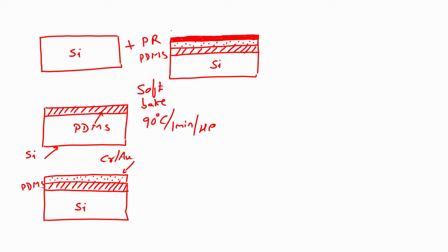After soft bake, I will load the mask to form my chrome gold pattern, and this mask will be a bright field mask. All right.